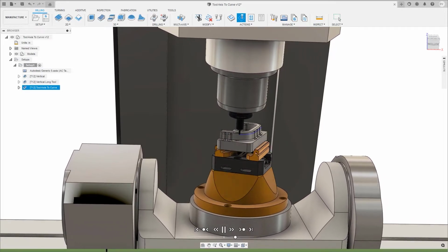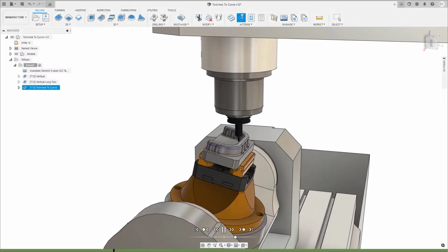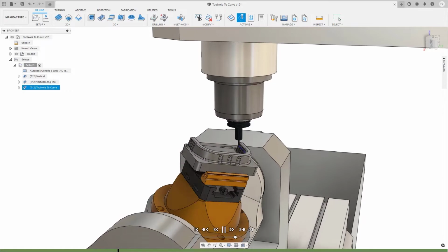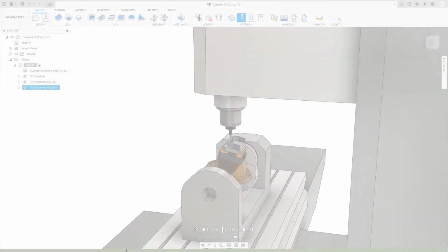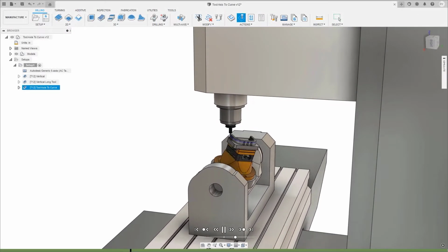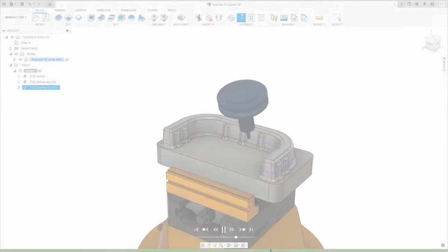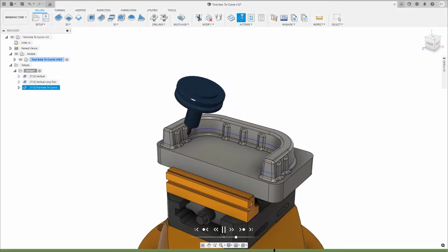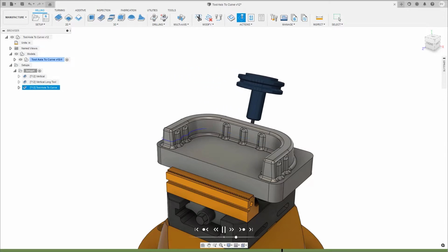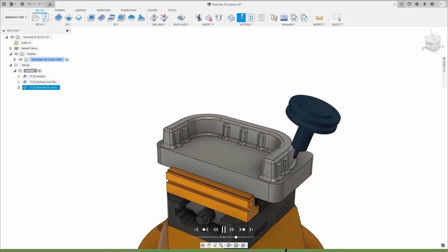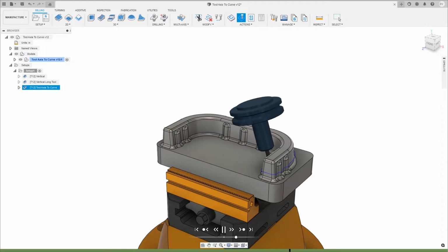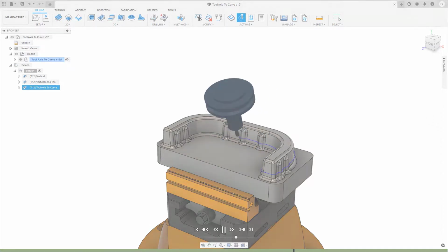Defining this tool axis, therefore, is a crucial step during the CAM programming process, which is why Fusion 360 has a range of tool axis definition options that simplify the process, leading you to quicker success. Here, we are going to look at how a tool axis can be defined so that its orientation is aligned to a curve. This often works well on part shapes where the curve follows the form of the part, such as the centerline of this form die insert.